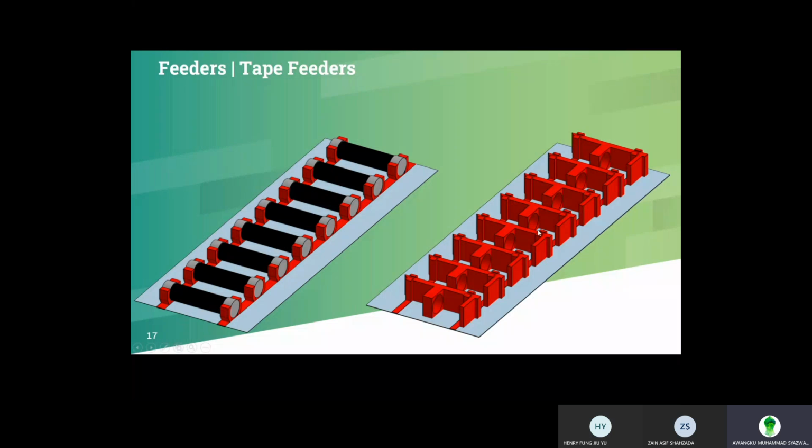For the tape feeders, they are on the opposing sides of the jig, and they house the fuses and the fuse cover. In the assembly process, which is in the final stage, the fuse will come into the fuse cover first before being transported onto the main case, which will be tilted on its side by 90 degrees, which we will see later, which makes it easier to insert into the casing.